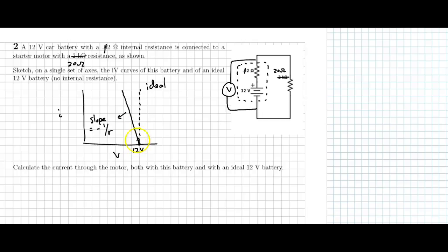Alright, so low current, we're pretty close to ideal. If we start to get high current, then the voltage really sags, which is how batteries work. So you can't ask too much of your battery. Like you couldn't put 8 1.5 volt double A's together and try to start your car, because trying to pull all that current through the battery will really cause that voltage to sag, and you won't be able to maintain that current. So that's one of the things that the car battery has over those other ones.